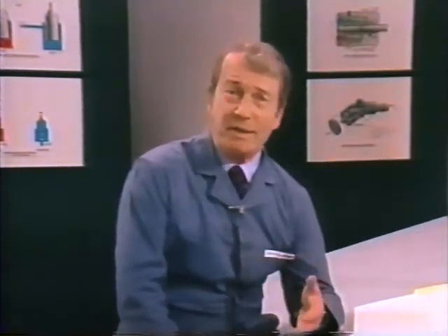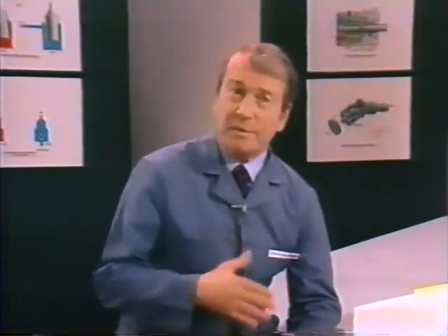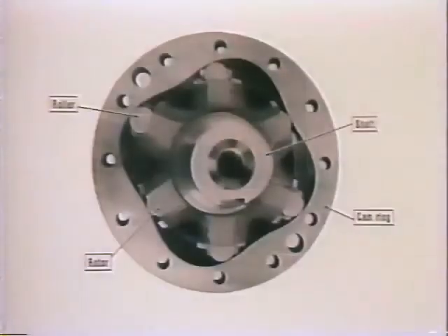Last but not least, we have the radial piston motor. Radial piston motors, while not as common as those previously mentioned, are found in applications where low speed and high torque are needed. Many of them resemble pre-jet aircraft engines, where pistons are assembled like spokes in a wheel. This motor, offered by Sperry-Vickers, has 6 pistons, each having a single free-spinning roller, which follows the inner contour of a 4-lobed cam as fluid is introduced through valving in the pintle to the piston chambers.